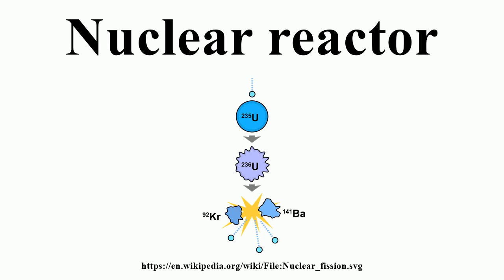Heat generation. The reactor core generates heat in a number of ways. The kinetic energy of fission products is converted to thermal energy when these nuclei collide with nearby atoms. The reactor absorbs some of the gamma rays produced during fission and converts their energy into heat. Heat is produced by the radioactive decay of fission products and materials that have been activated by neutron absorption. This decay heat source will remain for some time even after the reactor is shut down.